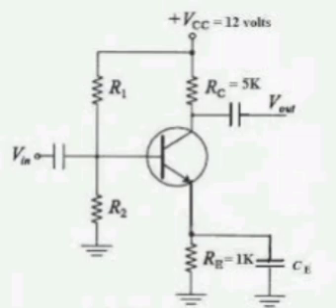Given IFSD equal to 1 milliamp, Rm equal to 100 ohms, RH equal to 2000 ohms, E equal to 3 volts. R2 equal to IFSD Rm RH whole by E minus IFSD RH, R2 equal to 200 ohms. R1 equal to RH minus IFSD Rm RH whole by E, R1 equal to 1933.33 ohms.